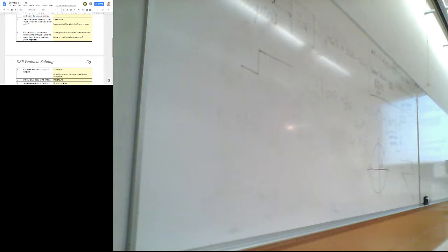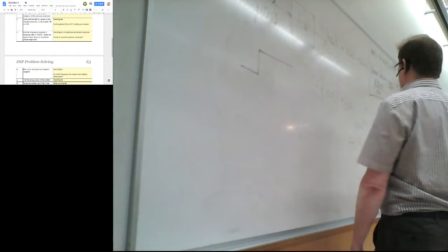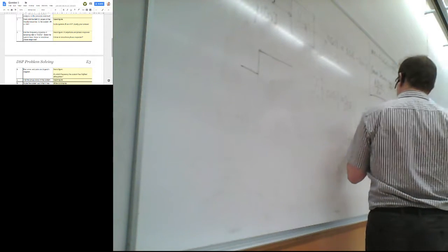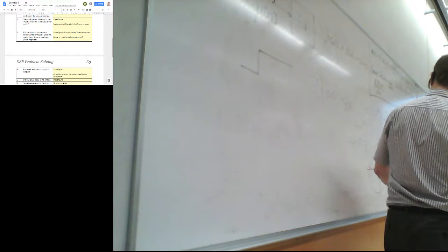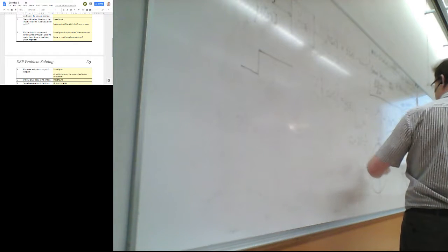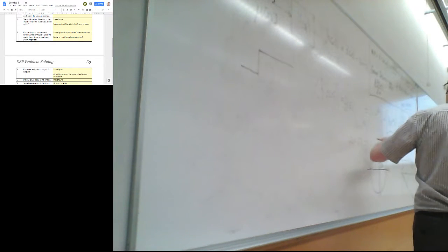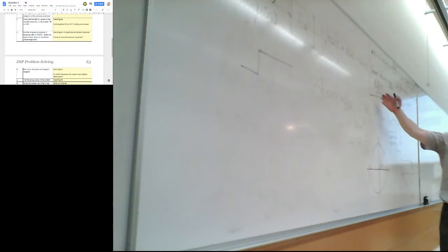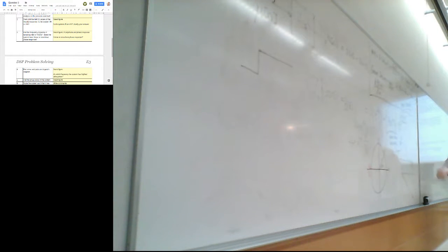Okay, there we have some responses. So we have a frequency response, which is simply the transfer function evaluated at the unit circle, where this complex angle actually gives the physical frequency. It's directly proportional to the physical frequency. Then this one is a complex number, but for plotting, it's good to know what the amplitude response is, meaning what kind of filter this is, low pass, high pass, how much stop band attenuation it has and so on.